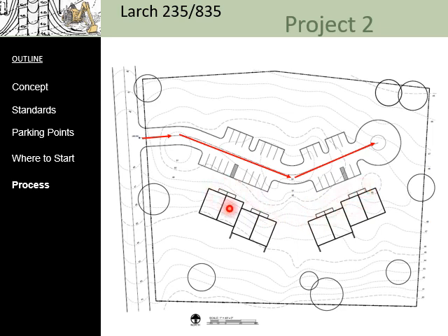And that gives you a huge amount of flexibility because if each stair is 6 inches, you add 2 stairs, you'll gain a foot. You do not want to be walking down the stairs into these buildings because then you might have a drainage issue. But if you want to come up a couple of stairs in order to correct things in the back, that's perfectly acceptable. Remember, you do have basements on these buildings, but not all of them have to be walkout. You're also allowed to have stairs in the front, but you can't have stairs in all of them because at least 2 of the townhouses have to be ADA accessible.